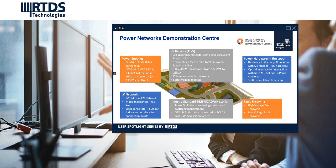That's used as an interface between the real-time simulator and the medium voltage 11 kV network and low voltage 400 volt network in order to implement the power hardware in the loop test. And of course, a 6-rack RTDS system where the network model is deployed.